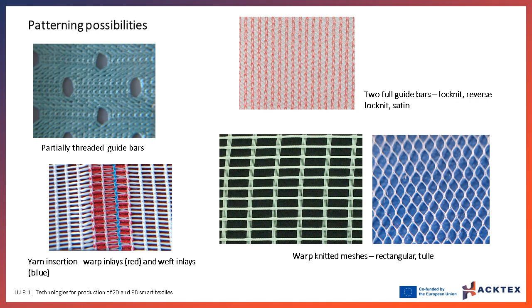Warp knitting technology is suited for weft and warp yarn insertion. Mesh structures are opened fabrics with preset geometry, that can be obtained using pillar and weft inlays, with the possibility of including other inlay yarns for patterns.